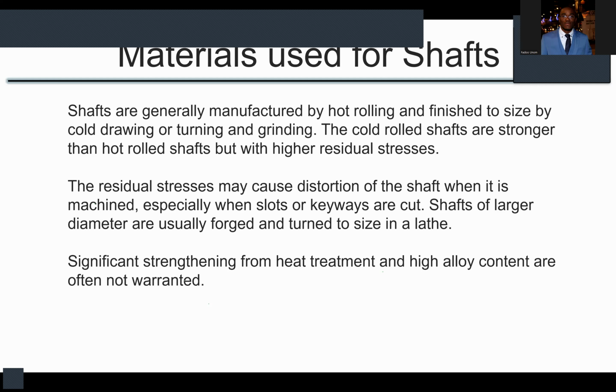And then, in the use of the shaft, new stresses were developed. At the point where you have residual stresses, those stresses add. The other points where there were no residual stresses can cope, but now the stresses are beyond what the material can take, and then it fractures, it fails.